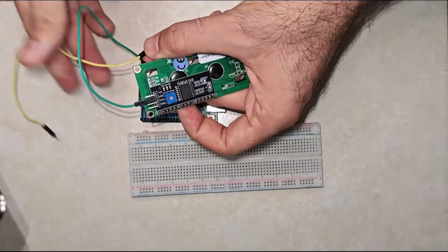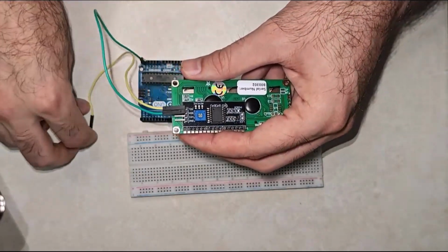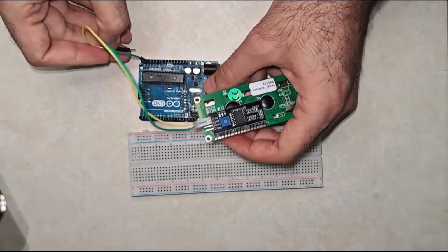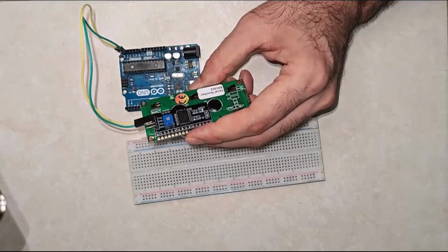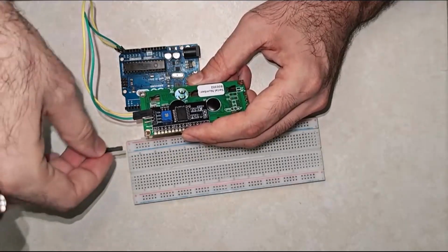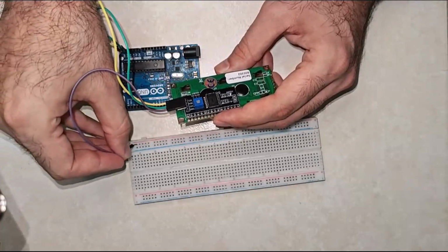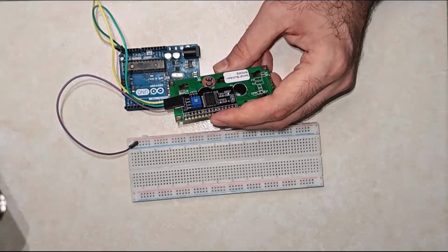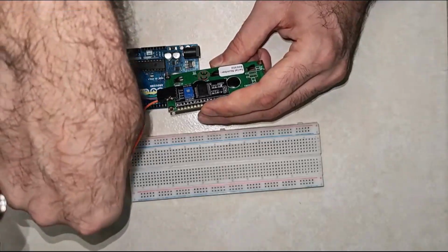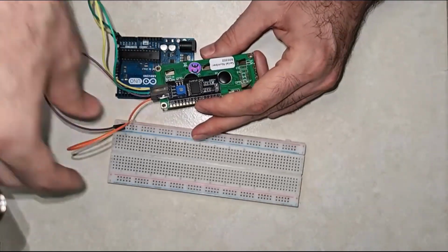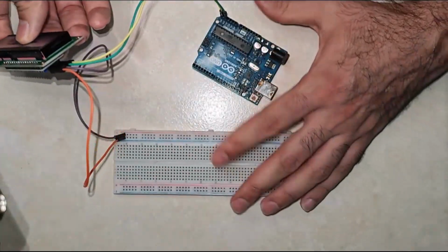Let me connect the wire. Okay, so SCL will connect to pin A5, for example, the last pin. So these are the 2 pins. And like always, VCC means the 5 volts, or the positive. This is the VCC, and the GND will also be the negative. So I'm going to connect it to the negative row of my breadboard. Okay, so easy, guys. So this is the wiring.